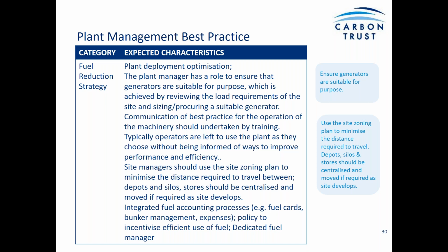Also, obviously, the use of fuel is very dependent on the distance of travel. So there's work to be done to plan how to operate the zones on the site to minimize the travel distance between the depots and the stores and the silos. Obviously, if it's a large site that's going to be there over a number of years, then you may well have to plan to move where the site accommodation is as well.